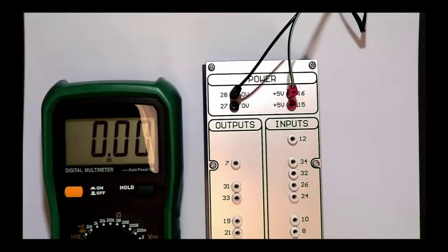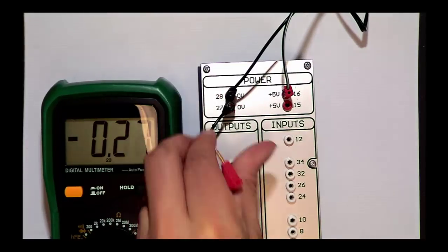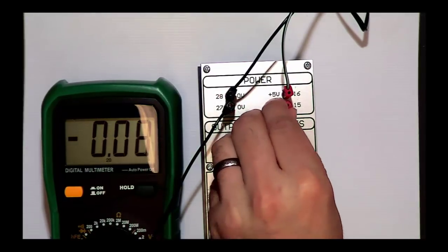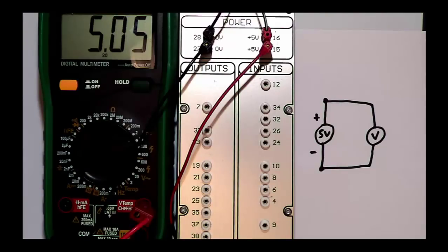Here we are going to measure the input voltage to the test board, which should be 5 volts. We will place the black probe in the 0 volt connector and the red probe into the 5 volt connector. We can map the schematic for this circuit to the real-world version as we did in the schematics and datasheets lecture.